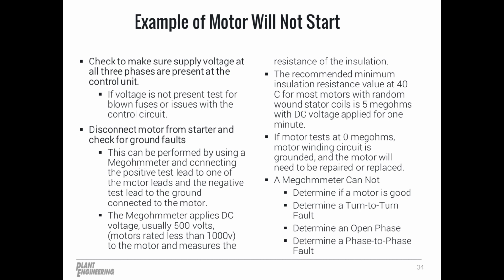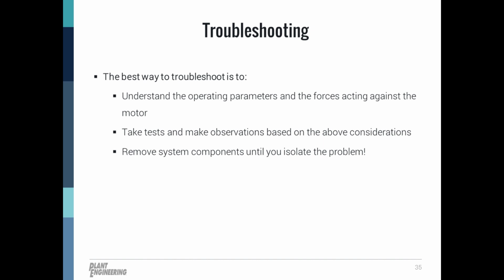Please note that a megohm meter cannot determine if a complete motor winding circuit is good, nor can it determine turn-to-turn or phase-to-phase faults. These tests will need to be performed by more advanced motor circuit testers.